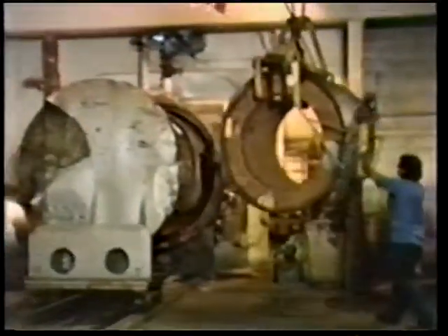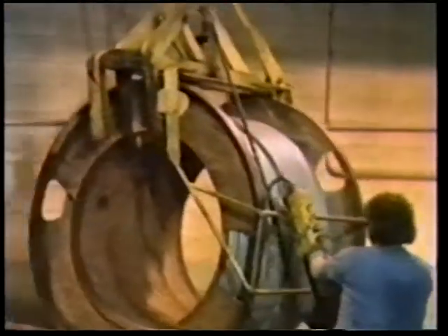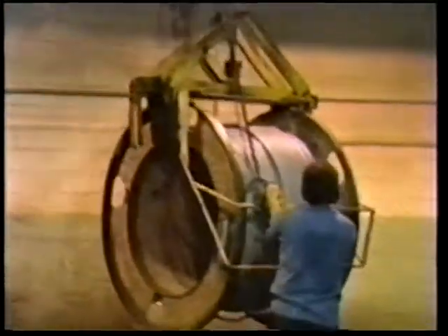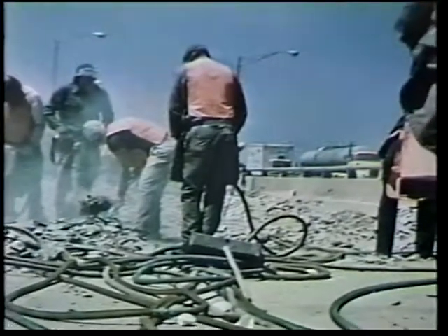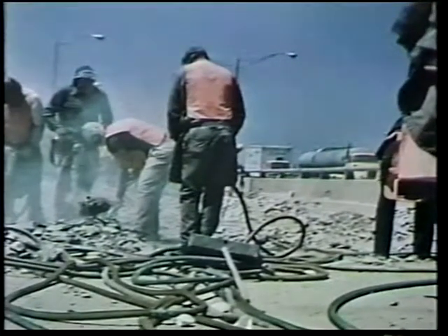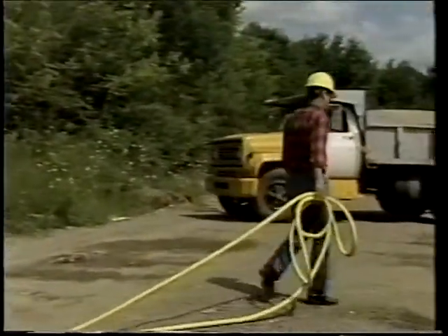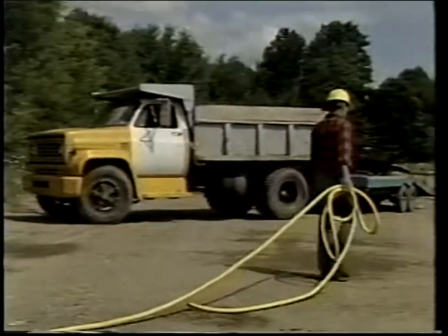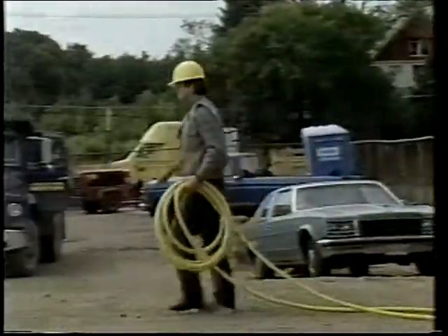The purpose of vulcanization is to cure the raw rubber and make all component parts homogeneous. This construction is very economical and is common for air and water hose. It gives the advantage of long continuous lengths in diameters of 3/16 through 2-inch ID in low to medium range working pressures.